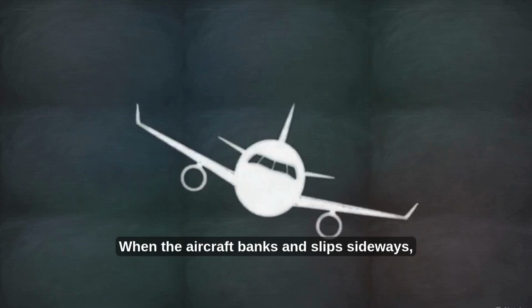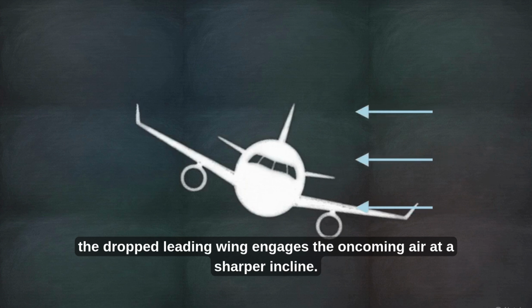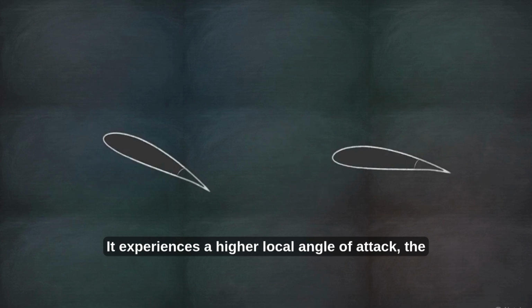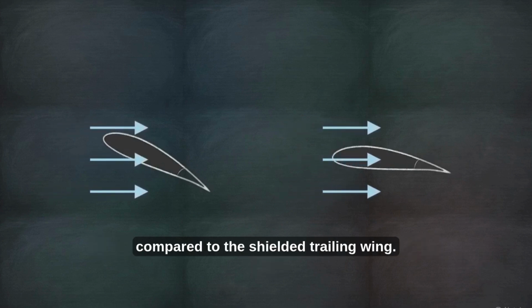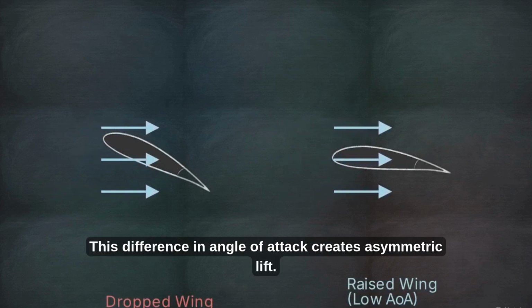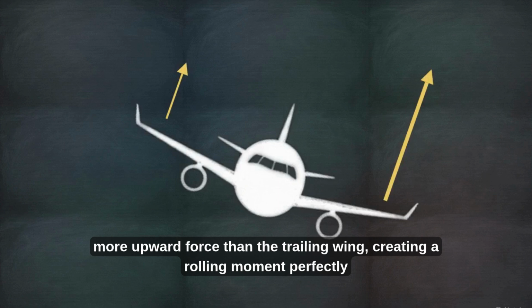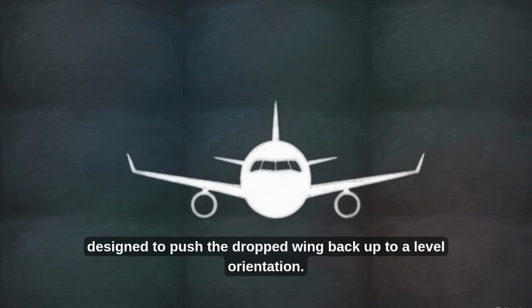When the aircraft banks and slips sideways, the dropped leading wing engages the oncoming air at a sharper incline. It experiences a higher local angle of attack, the angle between the wing's chord line and the relative wind, compared to the shielded trailing wing. This difference in angle of attack creates asymmetric lift. The dropped wing generates significantly more upward force than the trailing wing, creating a rolling moment perfectly designed to push the dropped wing back up to a level orientation.